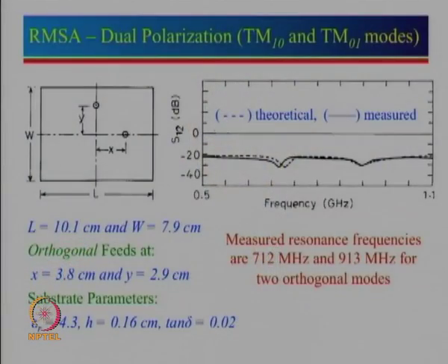Many times for channel capacity enhancement, we try to use both horizontal as well as vertical polarization. If you want to use both polarizations, then we can get signal from both sides, and what is important is isolation between the two. Generally, 30 dB isolation is considered pretty good.